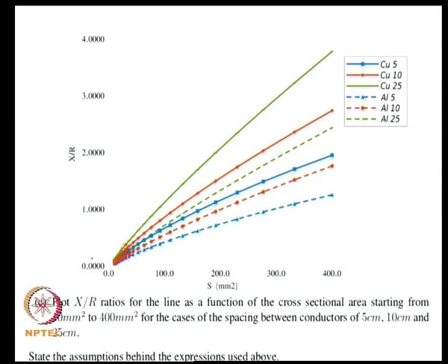So, at the consumption point within your house, within a small establishment, you can actually model the wire as a resistance. That would be a good approximation. Whereas if you go to the large cross sectional areas, you have a larger x by r ratio. So for your feeder, probably even at the secondary distribution, depending on the cross sectional area of the wire, you have to consider the inductive effects.